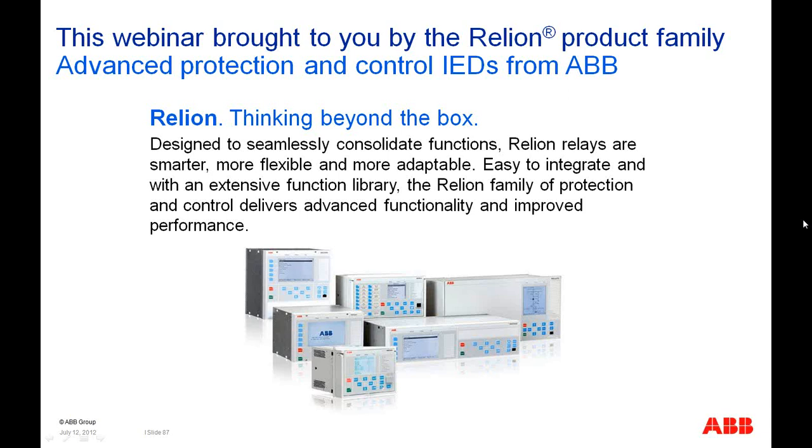I'm not quite sure about that question. Typically, I'm thinking you're shorting a CT through some sort of a switch. So if you're shorting the CT, it's not necessary to remove the conductors from the CT secondary terminals at all, if you're shorting it through a shorting switch, or through an FT switch type that ABB would make. And it doesn't matter if it's C or T rated as far as that's concerned.